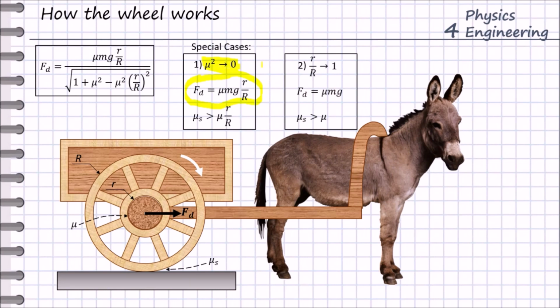So I believe we can definitely consider this approximation, because in reality the friction coefficient, especially for modern vehicles and modern systems where we have a proper surface finish and proper lubrication, this mu will not exceed 0.1, and then mu square will be like 0.01, and then we can assume this approaches 0, and we can use this simple equation, which is much easier to remember.